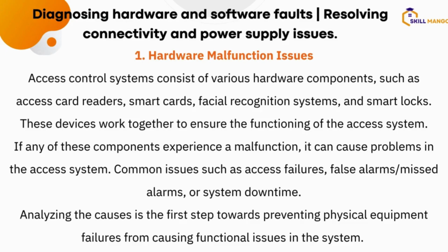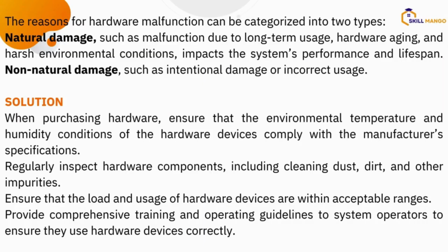Ensure you have the right power supply. If, for instance, total requirement is about 12 volts, 2 amps, you can do 12 volts, 4 amps, so you have redundancy. So you won't overload your power supply for it to fail or start giving you problems. All right, so you have to read up on the write-up to understand the theory better.